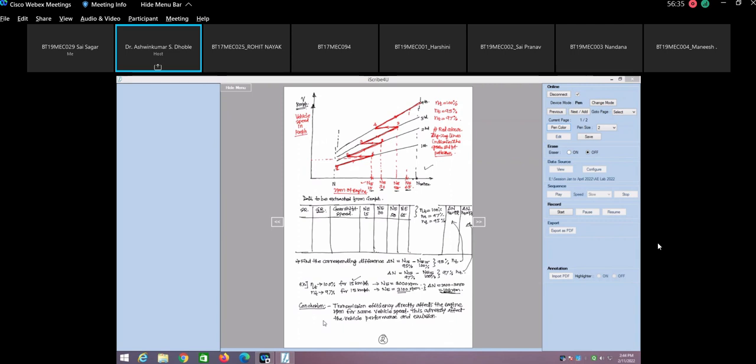Sir, remember another thing: the same thing, there can be a problem if you are operating the clutch by mechanical means. If there is some play in the linkages of the clutch operating mechanism, then such a thing can also happen. At times when you drive the vehicle, or if you are a co-passenger sitting in the vehicle, whenever the driver changes the gear and you feel a sudden jerk, then please understand that the vehicle has a problem with the clutch.